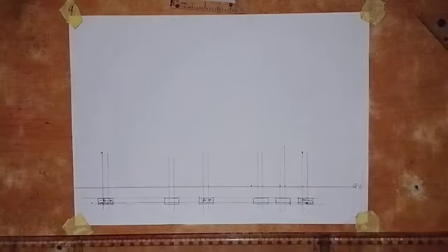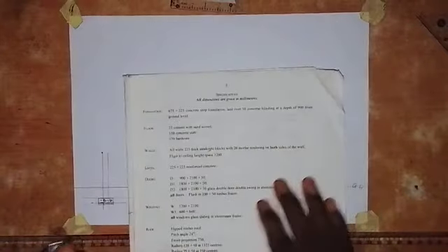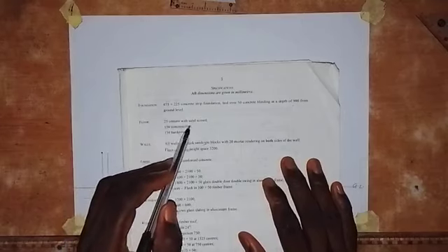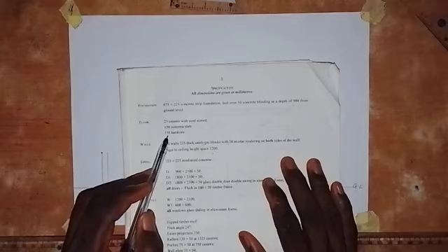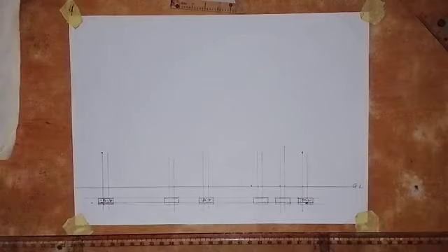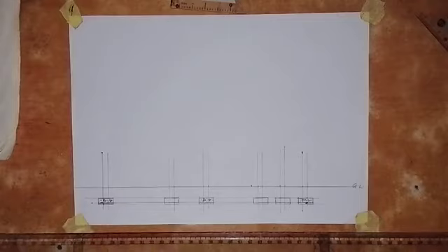The next thing that we are going to do is the floor. So for the floor, we have the components of the floor: 25 cement with sand screed, then 150 concrete slab and 150 hardcore. Each of them we are dividing by 50. We start with the hardcore. I'm going to assume that the hardcore is placed under the ground level, because no condition is given in the question.